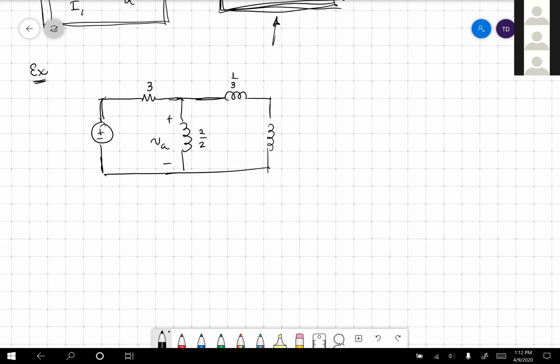We'll label this V1 for the primary. In general, these are not labeled. I'm putting it in right now. You have to identify the primary and the secondary. You get to choose which side is the primary side and which side is the secondary side. Remember, we can put these in, quote, backwards, and it's the same thing. It's just 2 different coils. What differs is the number of turns on the primary side and the number of turns on the secondary side.